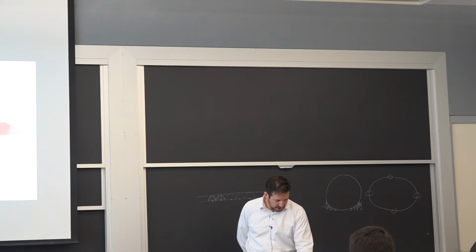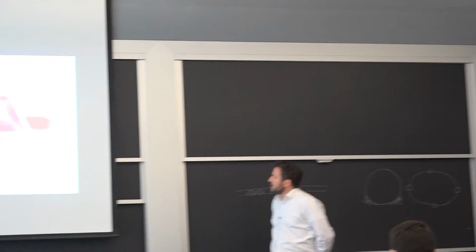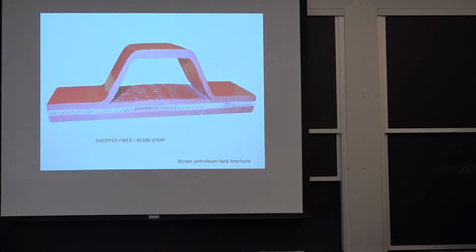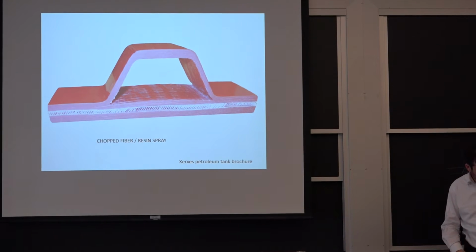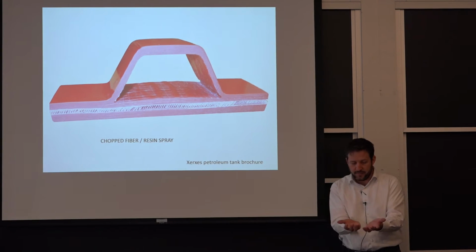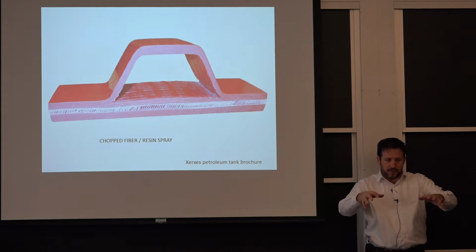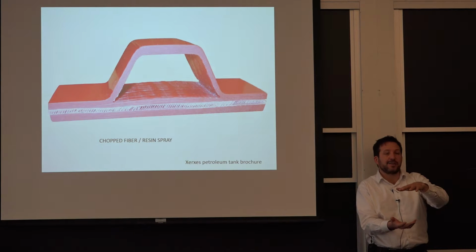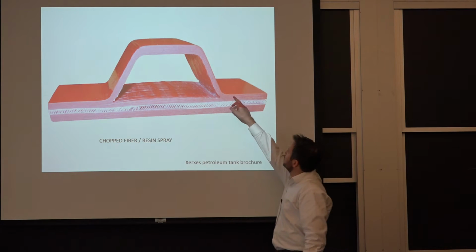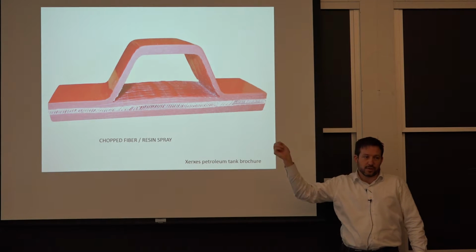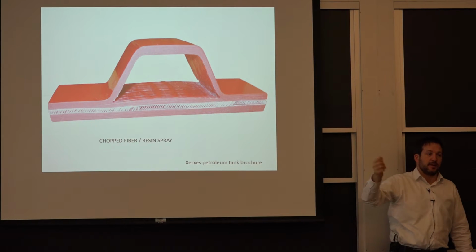You also, in the design, include these ribs. So you see they're not solid, they're empty. And so the way this works, just in terms of the manufacturing, is you have your form. You have two halves of a mold that is essentially the outside profile of the tank. So this one. And then you come from the inside and you start spraying the composite.